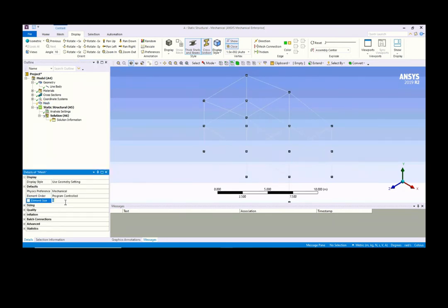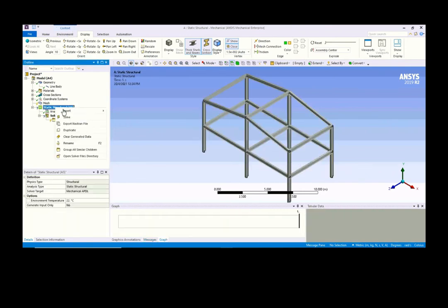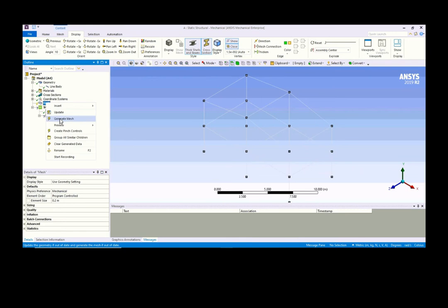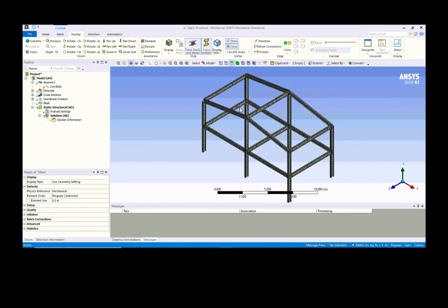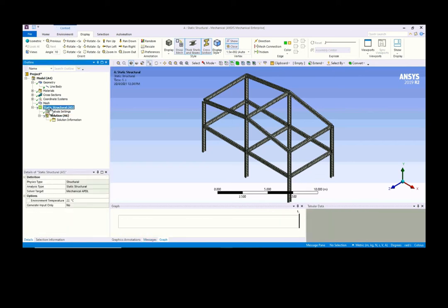In this case, we use 0.2 as given by your question. So if we use 0.2, then we click generate mesh, then basically it will give us something similar to this. Every 0.2 meter is an element. All right, so if you want to investigate how many elements, you go to statistics, that is 614 elements, 1220 nodes. Right.